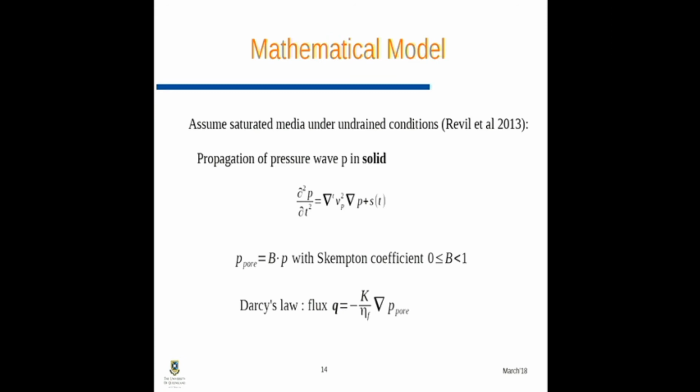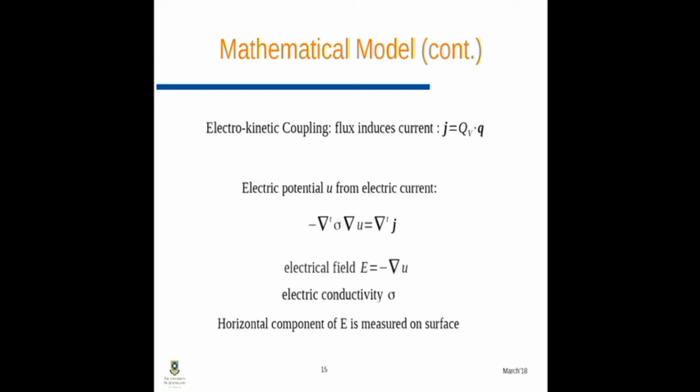So these are the equations you need to solve. It's a wave propagation equation, and there's a Darcy law for modeling the fluid flow. You can make a more complicated model actually simulating the propagation of the wave in the fluid, but because the friction is so high, you don't really see this. So this very simplified sonic model, which is propagation of pressure only in the solid, is sufficient in this model. And then you also have the simple electric potential equation to solve here.